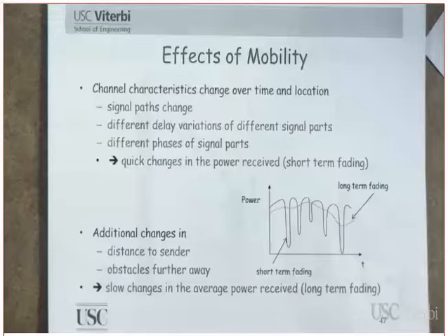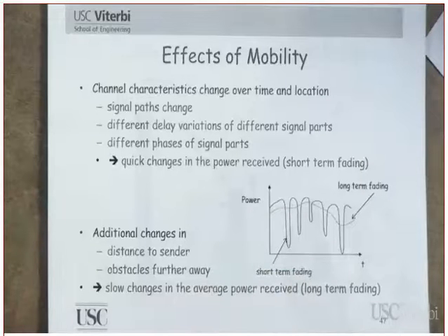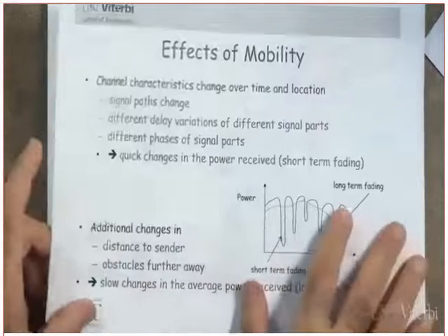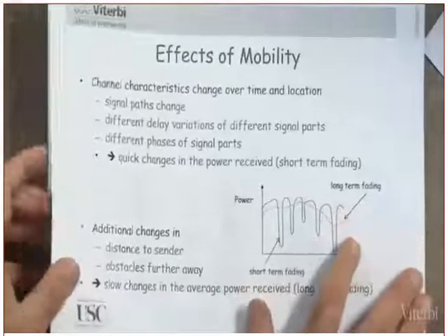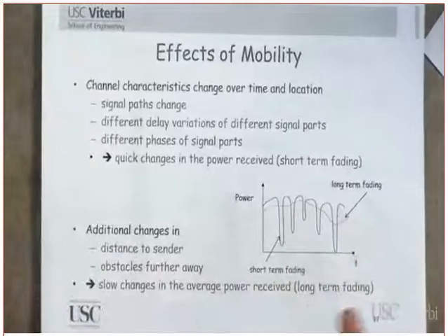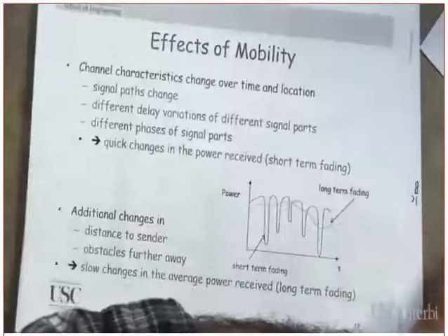Clear? Now you might say, but what difference does it make if you transmit them multiple times? Remember what I told you a moment ago. The channel is time varying. Maybe during that time it's not good, during the other time it's good. You could also have a spatial diversity by including multiple antennas separated by a certain amount of wavelengths, such that you are going to make the received signal add in a constructive way rather than in a destructive one. You will learn this one in 535. Clear? We don't get into diversity in this class. We don't have time. I just brought it to your attention so that if you take the class, it will help you.